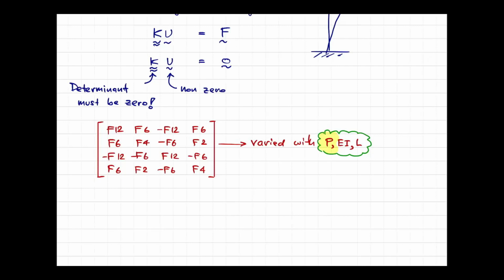So it doesn't simulate the real condition, and that makes your structure a little bit stiffer than the actual structure. So the numerical solution will be stiffer. More stiff means you have higher frequency, higher stiffness, because your structure cannot deform in the way that it would like to deform in the actual situation.